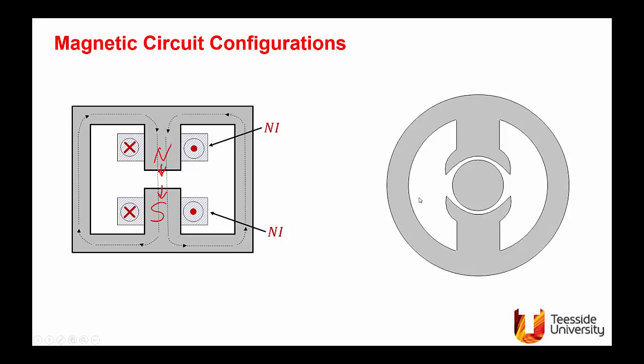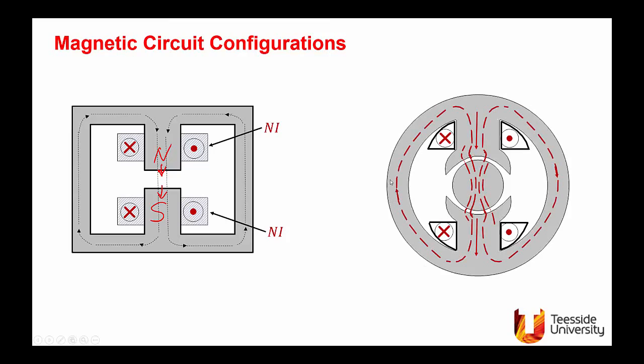First we insert the coils. We put the coils like that. We end up with the flux line like this. Of course, they are not just like that. They close around themselves, so the flux line will behave like this. You have to remember here that the flux lines enter the iron and leave the iron perpendicular to the surface. And if the surface has a curvature, then these flux lines will be radially oriented.